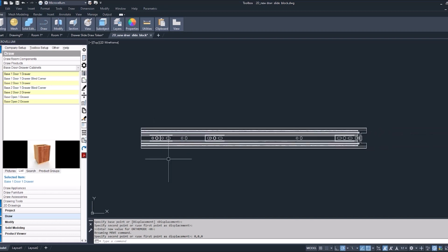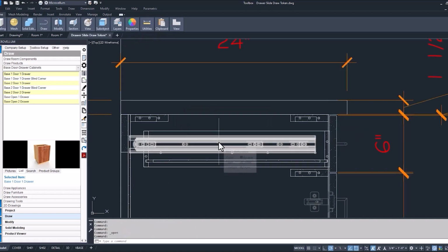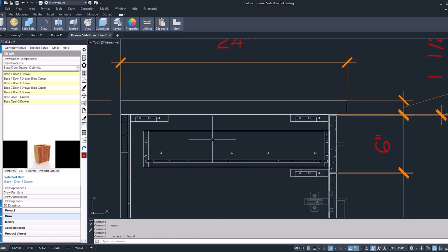You can also use the @ symbol to do that, but I've found that using that number sign or hashtag works better for some reason in AutoCAD. I don't know why, something with like absolute value. I don't know. Don't take my word for it, but it does work better. Now just save and close out of that DWG, back into our project. Make sure you select that drawing block that's already been inserted in the drawing. Delete that, because if you don't, this isn't going to work.